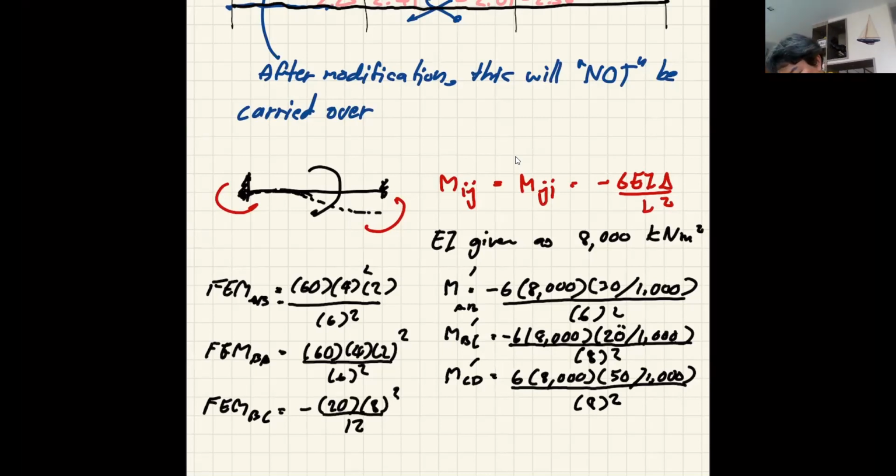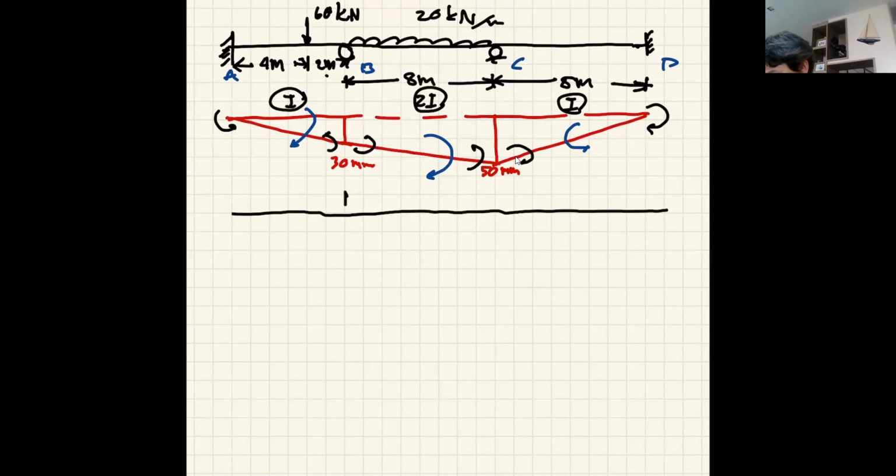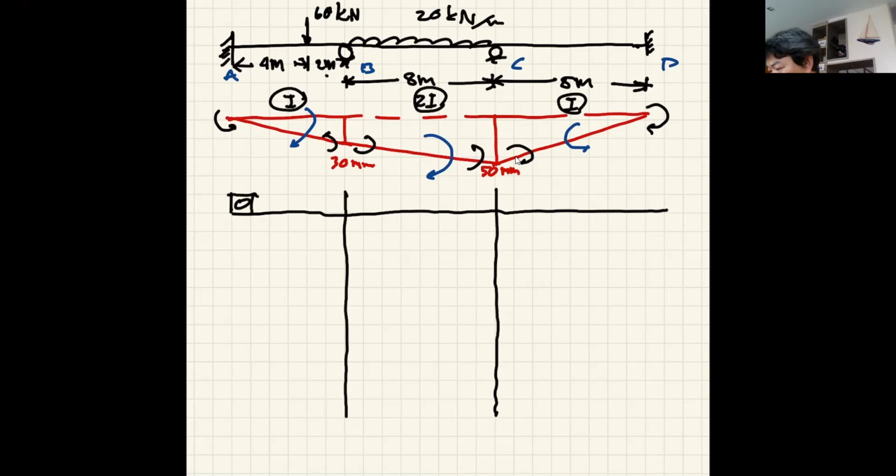There's no need for me to show anything about the relative stiffness. This guy should be straightforward. So I'm just going to put things into the table, okay? Not easy to try to make it straight, but I think I may have got it. And this guy is 0 because it's a fixed support. There is no lock and release process required because you already have the lock joint.